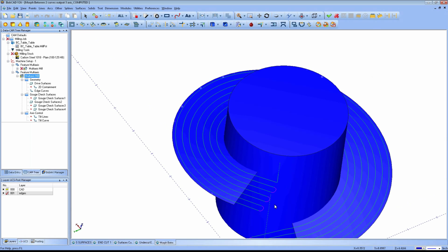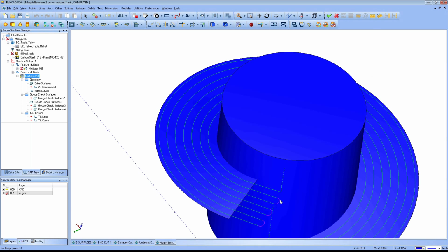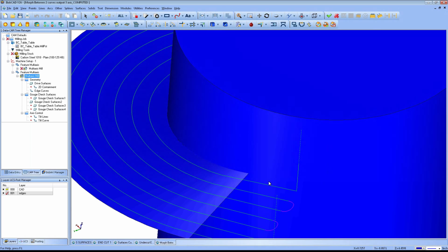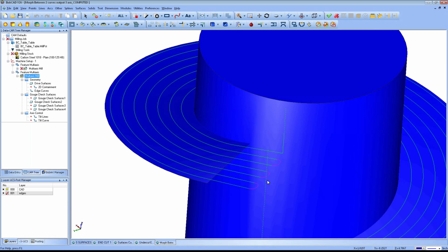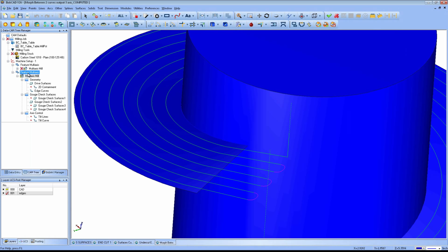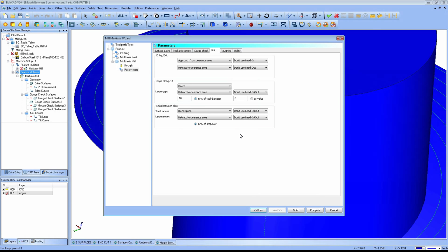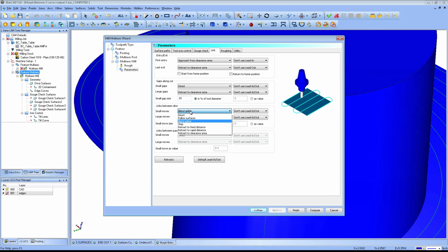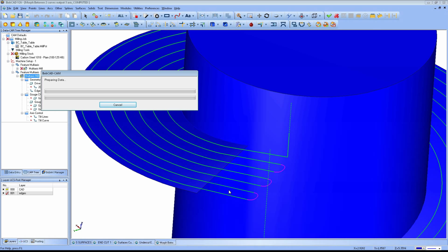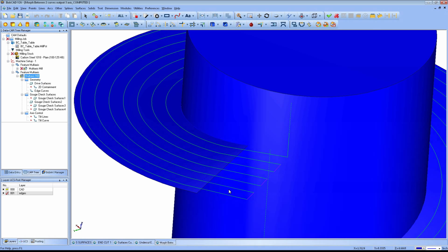And if you look at it, the blended spline would be the link type here, instead of a direct over. And we can show you an example of that. Let's zoom in so you can see these links a little bit better. And let's go in and make a change to them so you can see what happens. Let's go to the links page. So instead of a blended spline, let's do a direct and recompute it. And we'll give this just a moment. So you can see a direct is just like it says, direct connection.